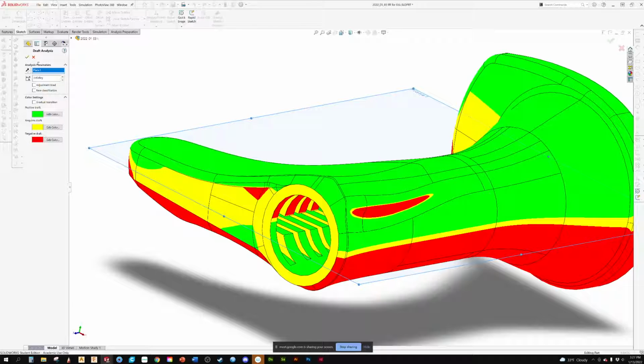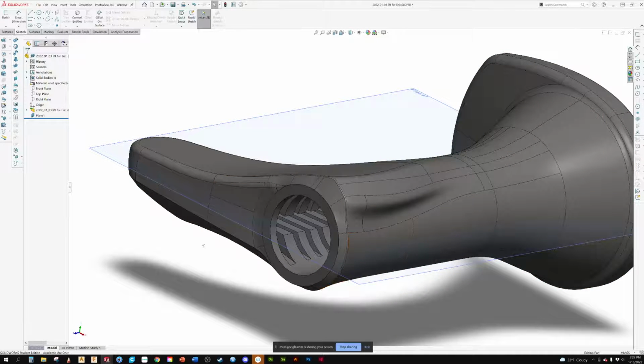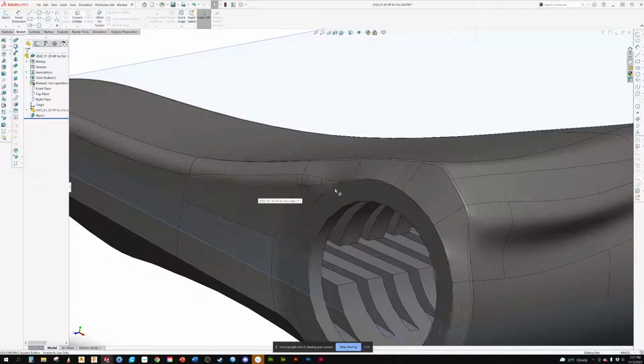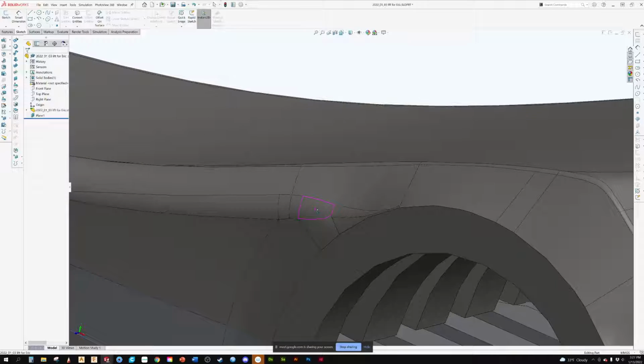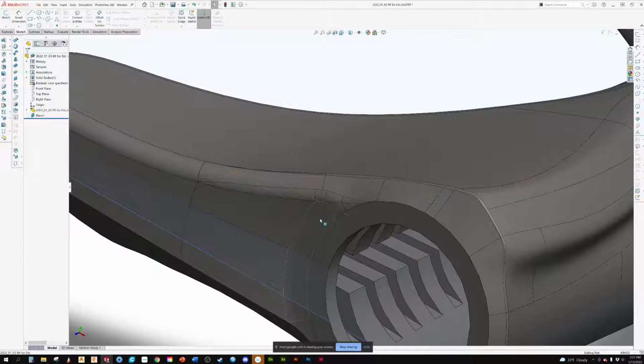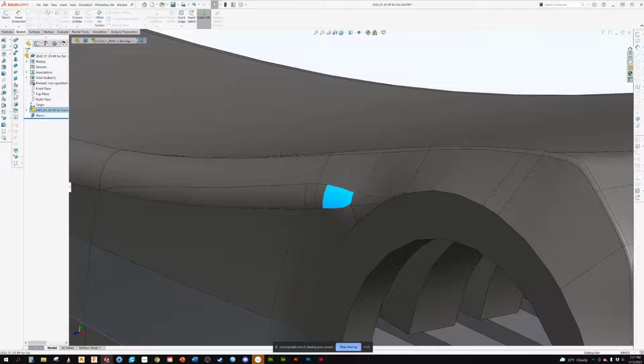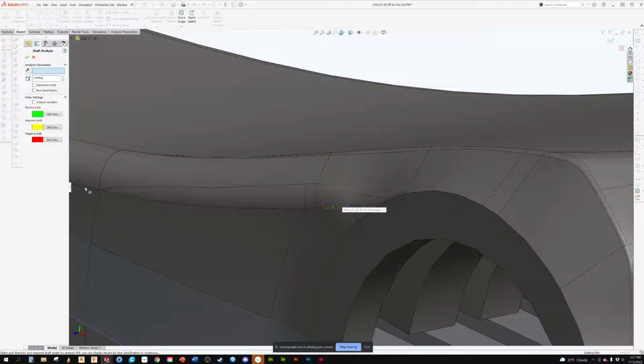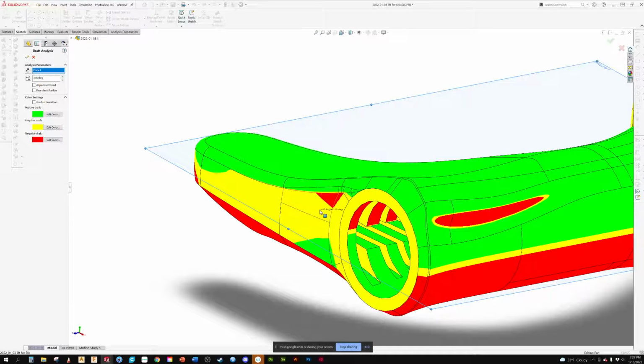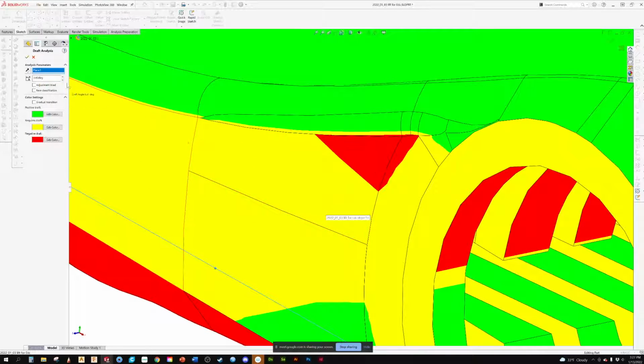So the challenge is now to come in and fix things. The first thing they wanted me to do before they said fix the draft was, you can see here something that everybody's experienced, just dropping in radiuses. It comes to a weird end down here. It's a whole bunch of weird stuff here. And all of this is what's causing some of that problem with an undercut.